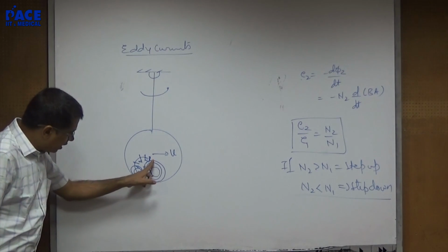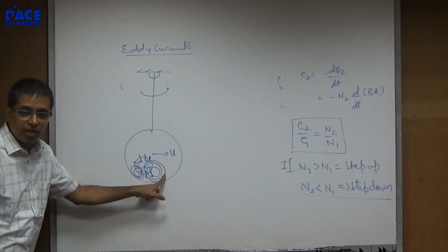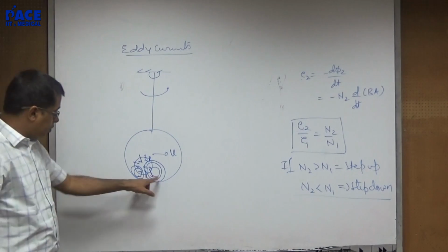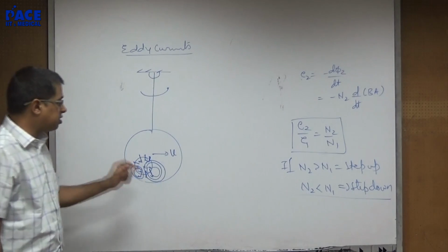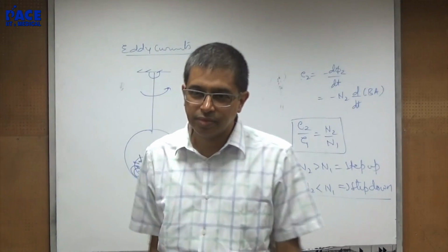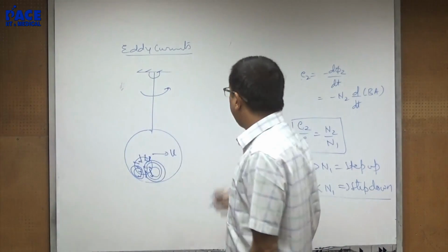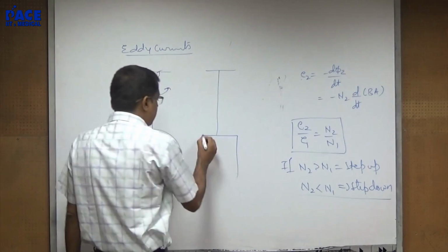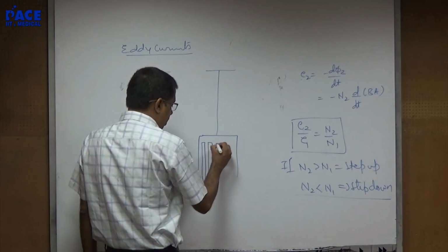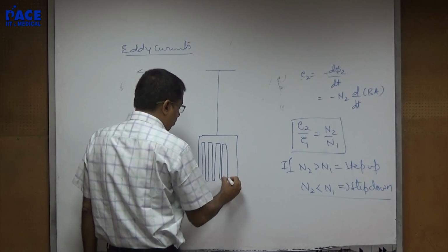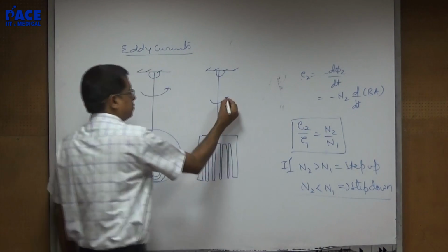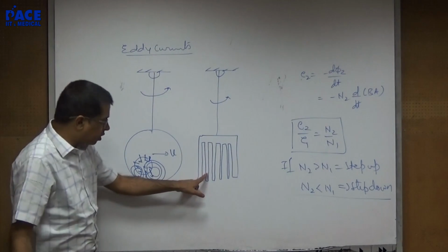What will be directing the electron to come back? The density of the electrons here, already existing density, will push the electron in its path. So the electron will complete the circle. This is unwanted current in the metal which will produce enormous heat. Hence, to avoid eddy currents, what do they do? They will take metal plates like this. If there are time varying magnetic fields, metal plates with many number of grooves in it, so that the path of the electron is destroyed.